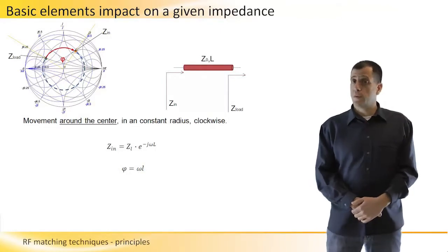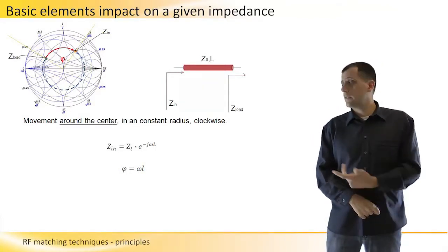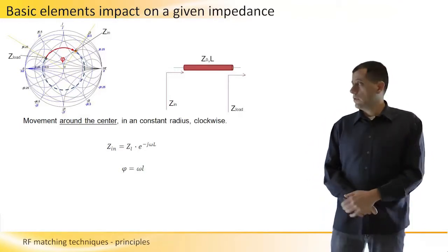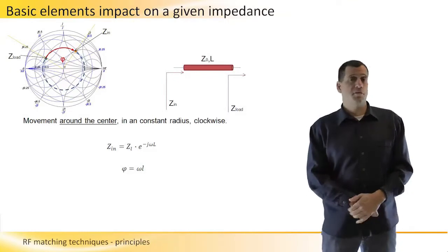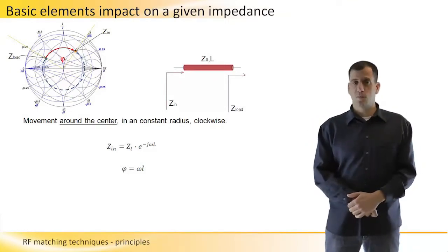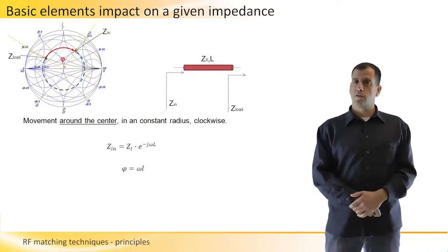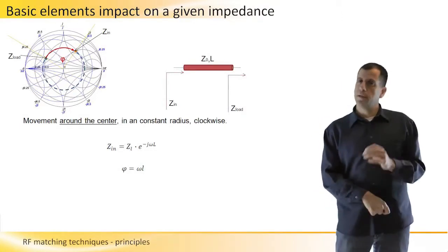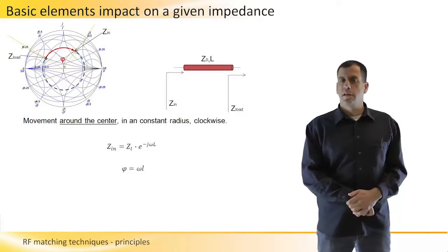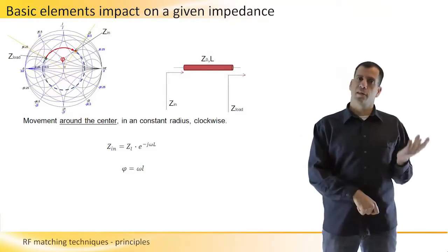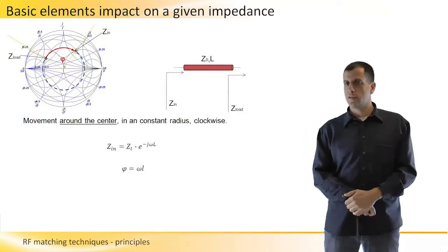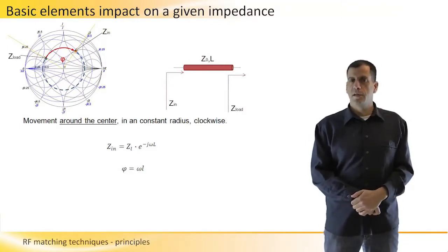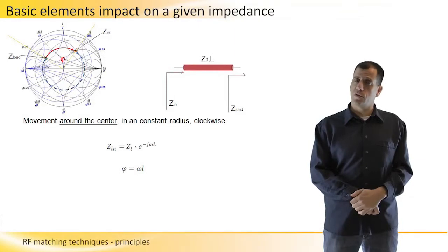And we have worked with an inductor and a capacitor and a transmission line. If we choose the components wisely, or if we choose the substrate or the transmission lines wisely, then the loss on these components that do the match of our system will be very small, relatively, for instance, to an attenuator. If we use an attenuator, of course we will do a matching, but we will pay a lot of energy and we will lose a lot of energy on this attenuator.